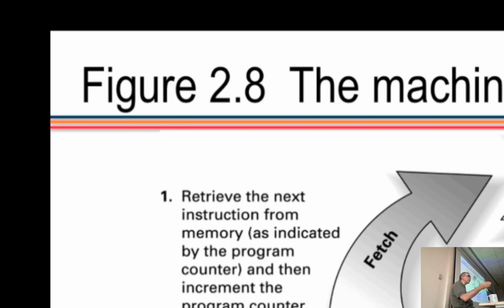And if there is a branch or go to, you will immediately go to a new address indicated by the program counter, because the go to instruction actually changes the program counter. Go to changes the program counter. And this machine in the next cycle goes to the other address because the program counter is now changed. So at each cycle it goes to the address where the program counter shows.